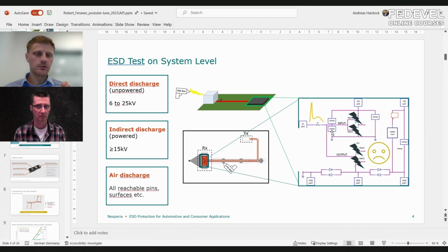We recommended ESD protection devices, and they put them on the PCB, tested short ESD pulses, and then did diagnostics and functional tests to look for even a little damage. Very good point.